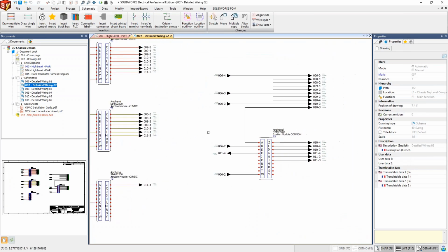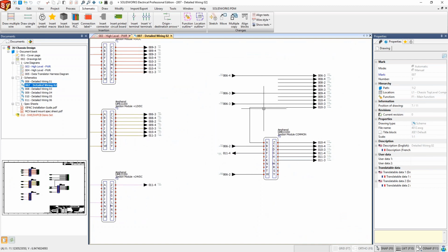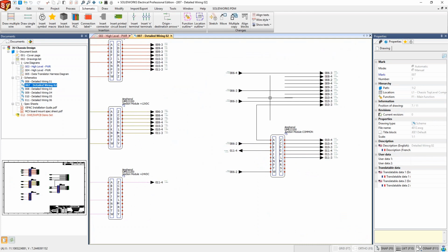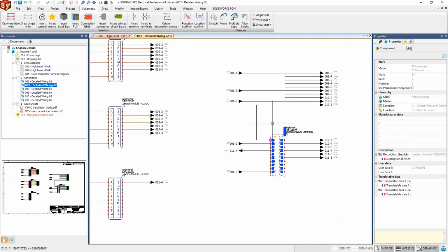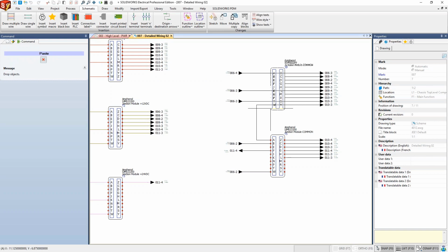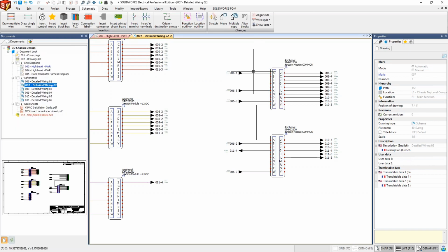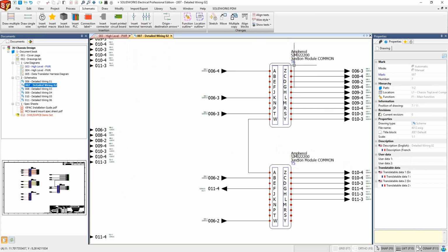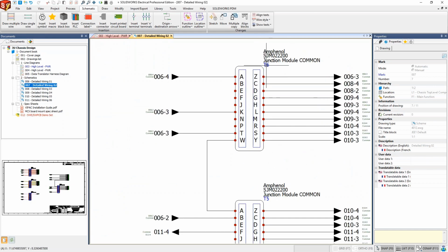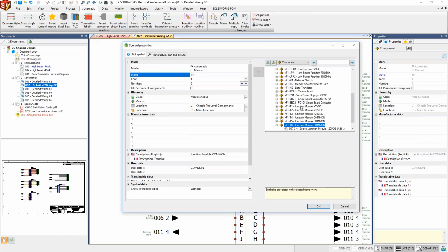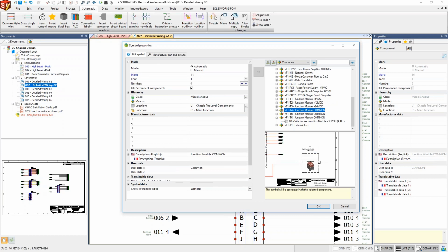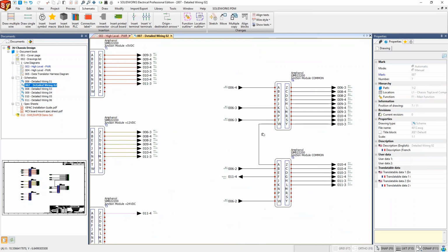And in this case here, we can see that I'm missing that same symbol, the T4. But instead of going back through my symbol library, every engineer's favorite feature, Control-C, Control-V, is still available in SOLIDWORKS Electrical, and I can very easily just copy it right in. And if you notice, as I said before, it did not overwrite any existing parts. It added T6. In order to change that, very simple. I'm going to find T4, and it gives me a quick little view to let me know, hey, this is T4. Do you want to connect this one and make those collaborative? And just like that, I now have T4 for that as well.